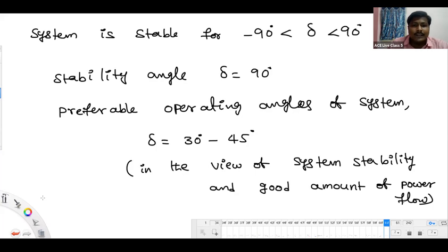Yeah. See, all generators used are synchronous machines. That's okay. Look here. All machines are synchronous machines only. But if you are going with other buses, maybe if you take, let's say, one of the generators as reference, other bus voltage angle might be negative, right? That may be a chance. That's why I'm saying in a concluded way, in what range of angles the system will be stable.